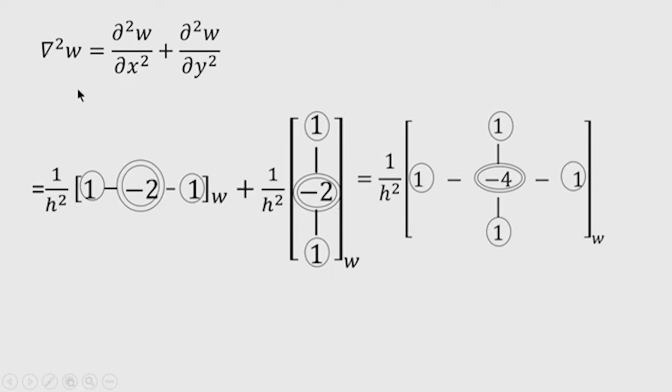Okay. Now, it is possible for us to find the finite difference form of the plate equation. How can we form it? Because we know the Laplacian operator. The finite difference form of the plate equation is found by writing del 4 W equal to del square into del square W. Okay.